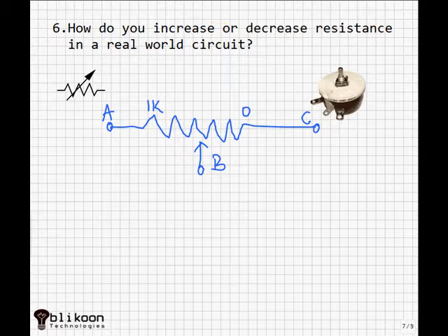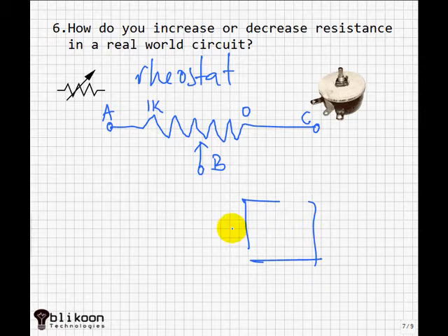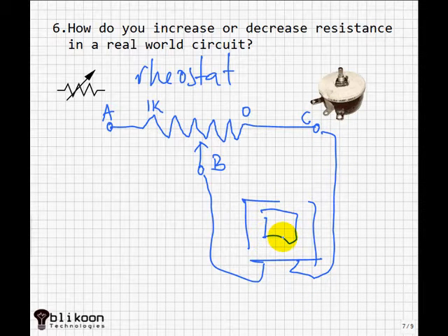You use a rheostat. A rheostat is a resistor with 3 terminals, like we see here, A, B, C. But B, the terminal B, is not static. It can move. And when you're using it in your circuit, you connect your circuit to 2 terminals. Let's say you connect these two, BC, to an ammeter somewhere. And you read your values on the screen here.